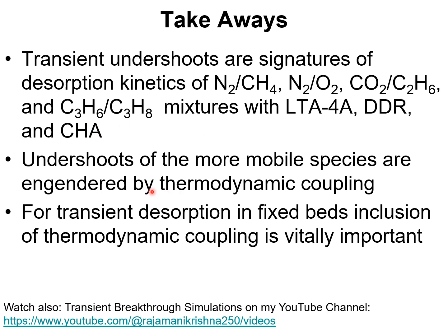In all 4 examples, we note that the more mobile species undergoes transient undershoots, and these undershoots are engendered by thermodynamic coupling effects. A conclusion that also emerges is that for transient desorption in fixed bed adsorbers, the inclusion of thermodynamic coupling effects is of vital importance.